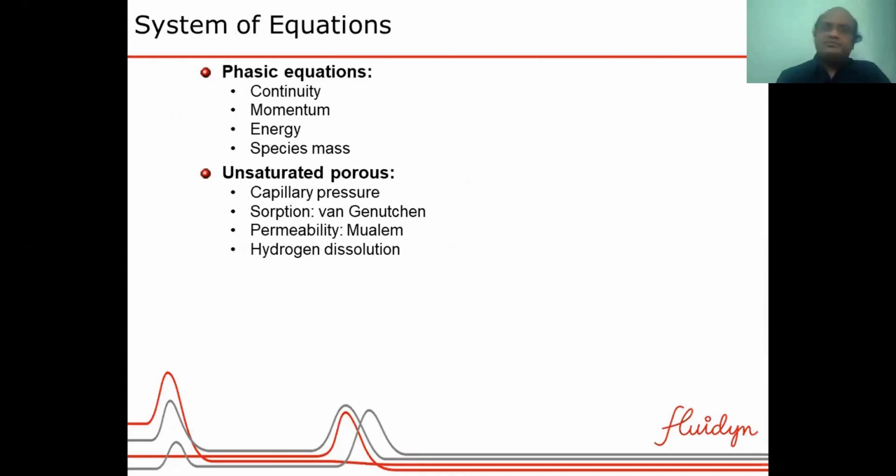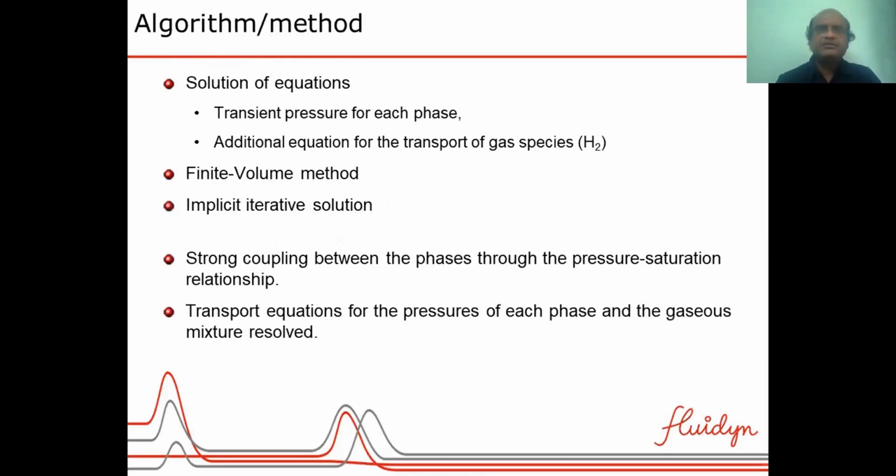This involved solving continuity, momentum, energy, and species equations for each of the phases separately. Flow and diffusion are to be considered through the porous media. There are different models for such things, which are different from the models normally used for gaseous diffusion and so on.